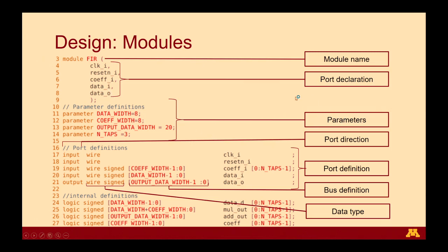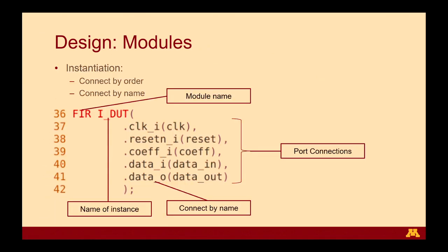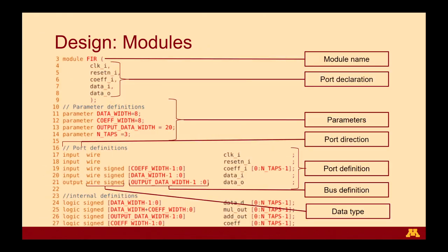So one thing which Verilog and SystemVerilog allows is parameters. In general, when we have these sort of designs, in most scenarios, not all factors of the module will be fixed, and they can be modified to suit different needs. In this particular case, the width of the data bus is not a fixed quantity, but can be parameterized to, let's say, a width of 8. But then this will depend on your requirements.